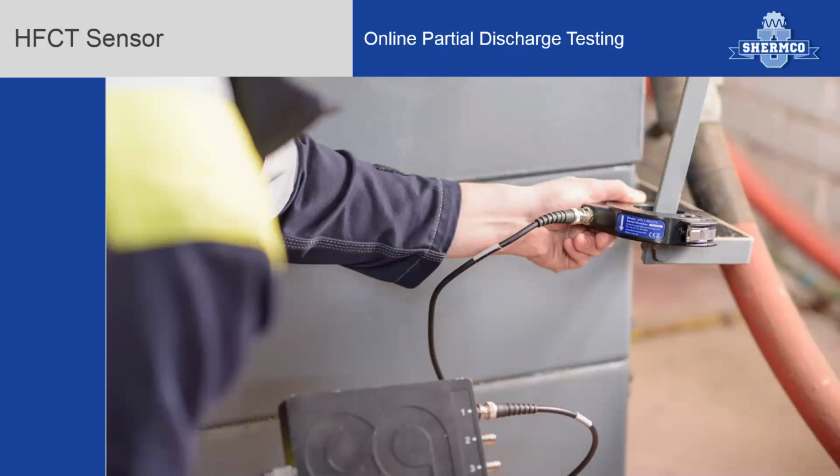So when doing a live online assessment, having the ability to adjust the bandwidth becomes very helpful for determining if we're looking at real partial discharge or if we're looking at noise being picked up. So again, that's an attribute of the receiver. A lot of times the CT will have a wide bandwidth, but the receiver will allow us to select certain noise filtering in order to determine if we're just picking up random noise from the environment or if we're actually picking up valid partial discharge emissions.